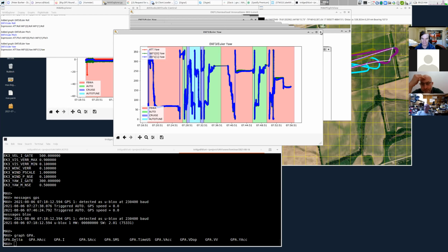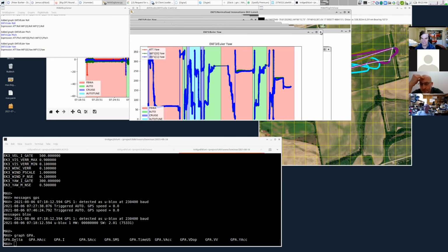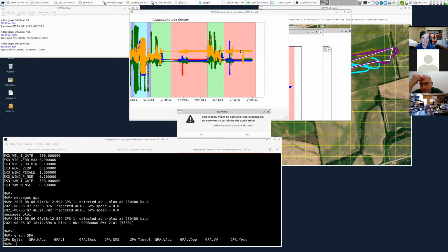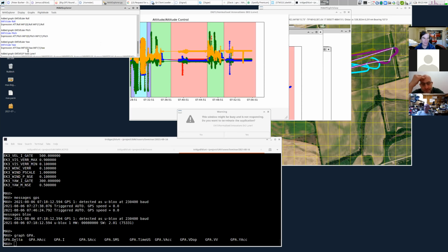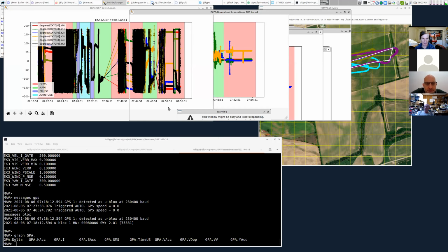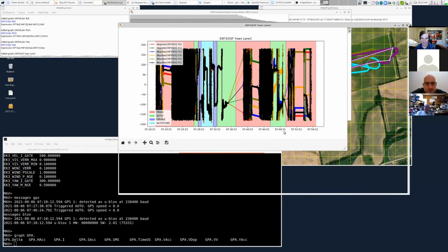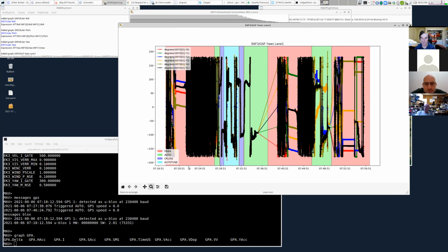We can also check the yaw. If we're worried that maybe the compass is pulling the yaw off, then you can look at the yaw from the Gaussian sum filter, particularly for planes. Indeed, we introduced that, which is something that doesn't rely at all on compass, so it's like an independent check. Yes, that's what Paul's talking about there, this GSF yaw element, which I'll just bring up. Okay, my machine's starting to get a little bit overloaded. What this is showing us is lots of yaw estimates and whether they've converged.